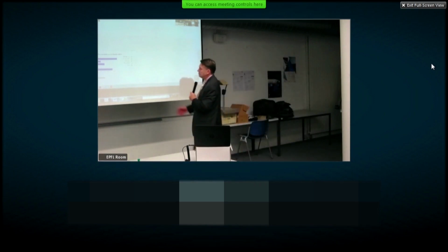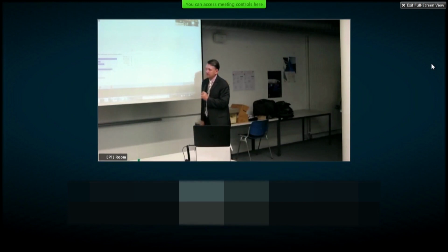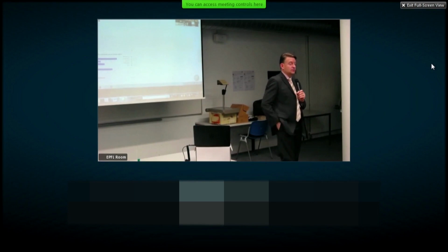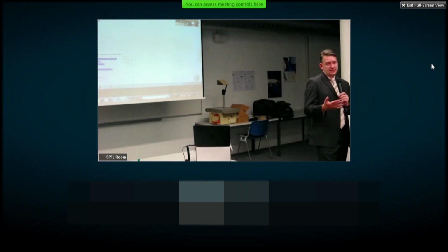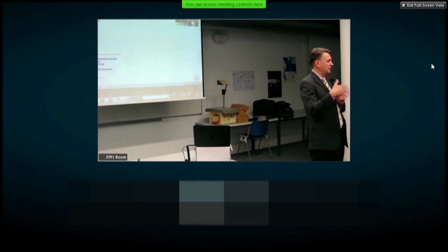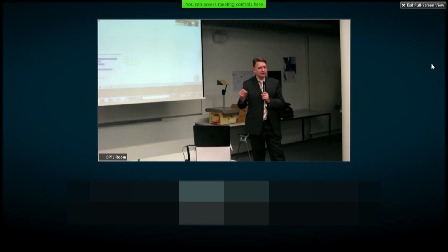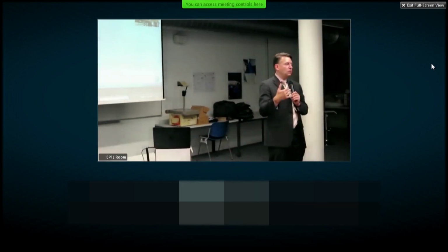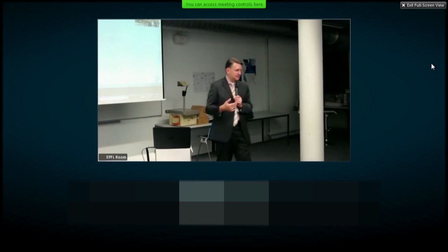Very important, obviously. MIL standard 1553, 24% know about that one. Anybody here at EPFL? MIL standard 1553? So you've done real engineering, I can tell. So what is the 1553? Yes, it's a DoD standard, so that's why it's a military standard. It's essentially a data bus. For example, on military airplanes, on many satellites, it's essentially the architecture of the avionics. It's a bus architecture, so you typically have a mission computer, that's the brain, and then it directs how the messages are sent from the different systems, like the flight control system or the payload. It's kind of an old standard, but it's a very robust standard for avionics architectures.